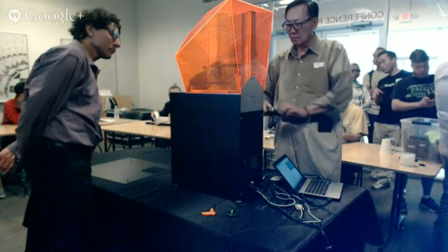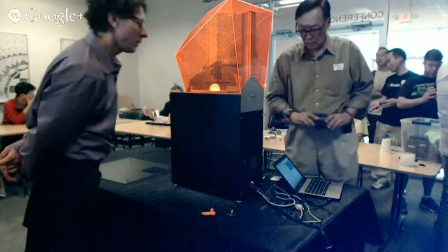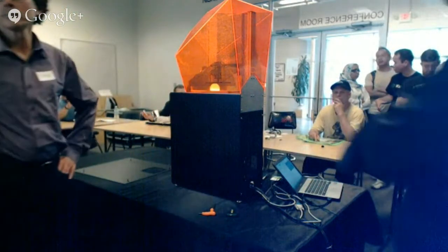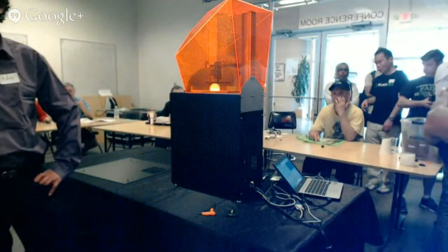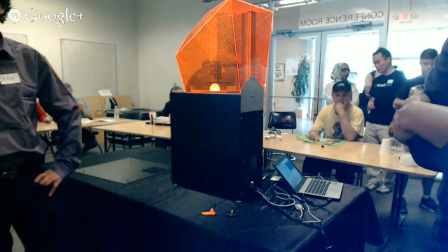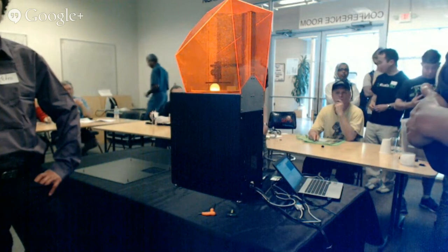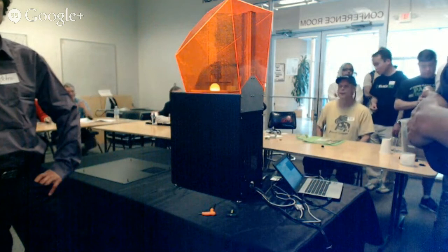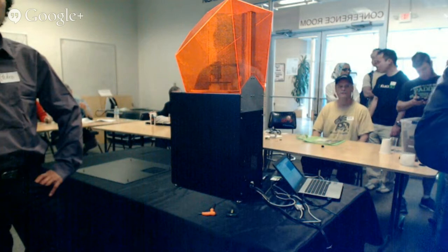With this much resin in the vat, it's not really such a big deal, right? Because bubbles are going to float up at the surface, meanwhile you're printing way on the bottom, and that's a big distance for the bubble to travel. The bubble doesn't want to go down, right? But if I were printing a small part and I put the minimum possible amount of resin in, where I only had like 1 millimeter of resin at the bottom, then yeah, I might have more bubbles.